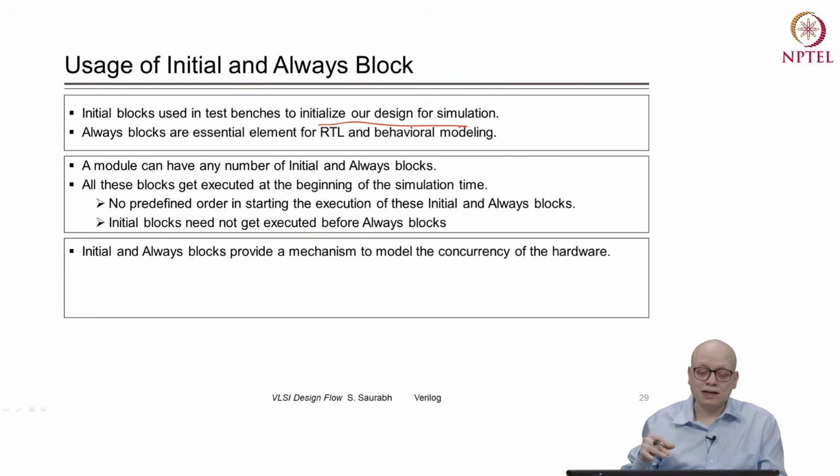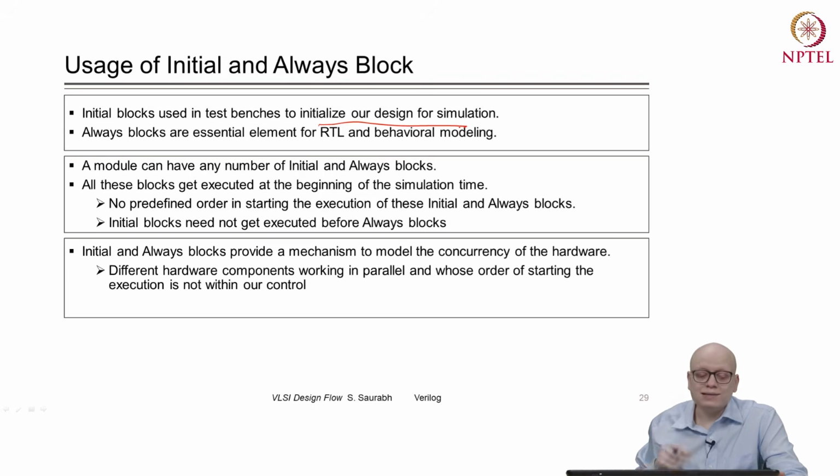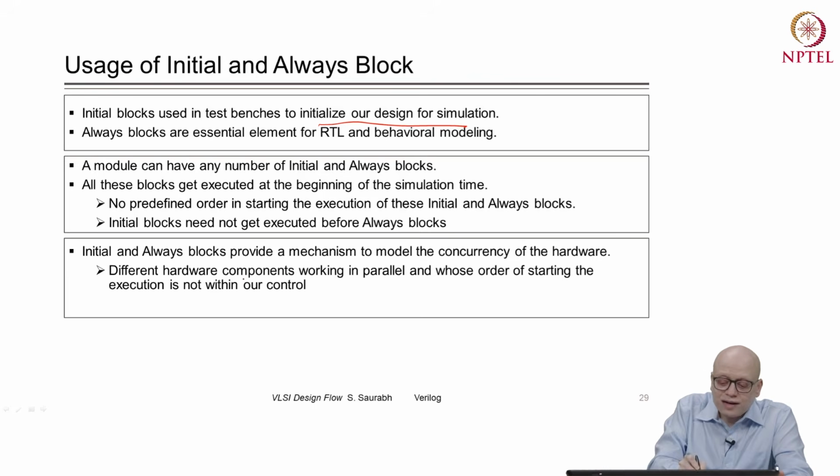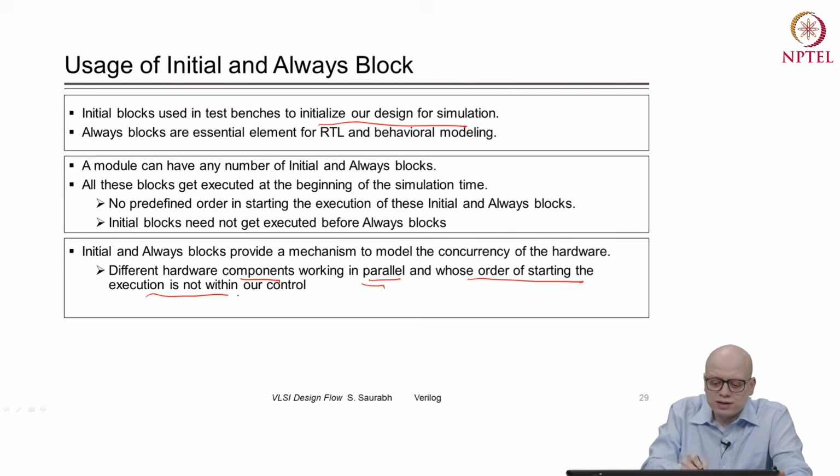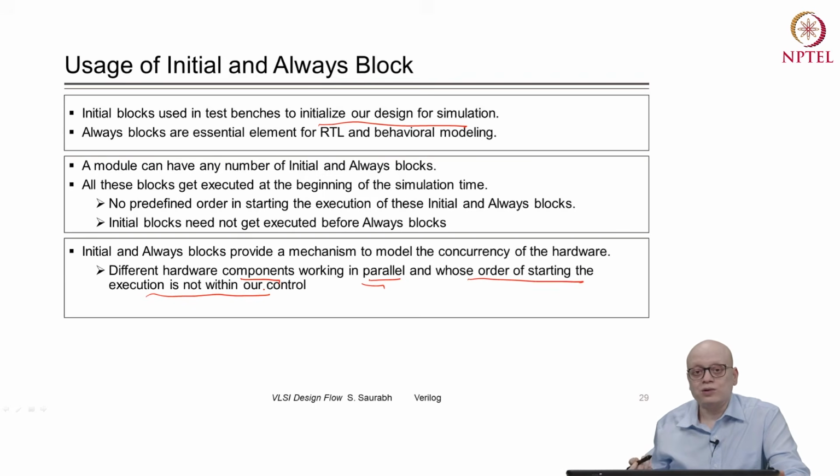And that is why the language says that there is no predefined order, considering that parallel hardware works in this manner. So, as a designer, we should think of initial blocks and always blocks as different hardware components which are working in parallel and whose order of starting the execution is not within our control.